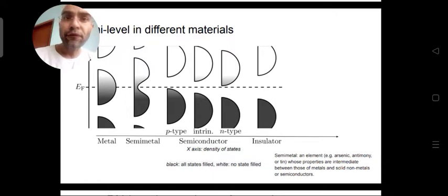As you have doped them, what will happen? The probability of finding the electron above it and below it should be 50%. So this is like the 50% level. You see what is happening, the number of charge carriers has increased in the valence band, so the probability will shift downward. So the Fermi level will shift accordingly. In a p-type material it shifts downward near the valence band, whereas in the n-type material it shifts towards the conduction band, because more electrons will be present there. So to balance this, to make the 50% probability, it will shift to a little higher side.